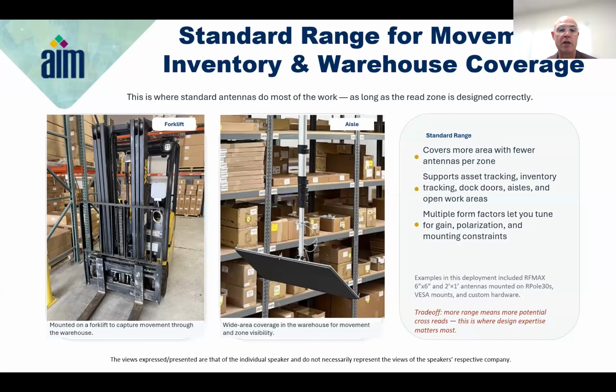And in order to read an RFID tag with a linear antenna, both the antenna and the tag have to be in the same orientation. When you're using a circularly polarized antenna, which again just means that this RF signal is spinning, then you could pack a carton with t-shirts. Each of those t-shirts could be tagged, and you'll read every tag regardless of the orientation within the box.